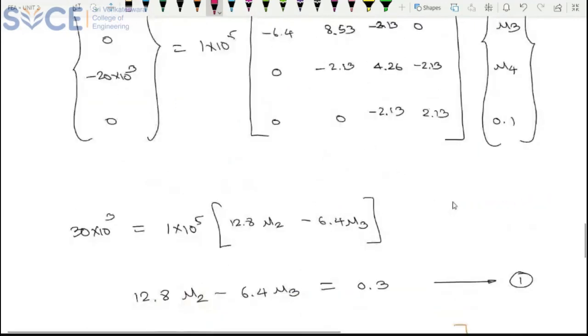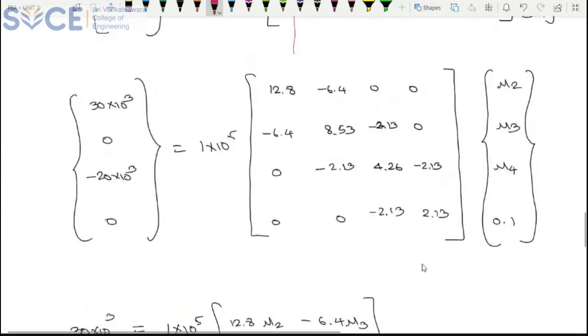Okay, don't use the last equation, even though you can get it as an equation. If you apply it, you have only one term, which is u4, so you will say that u4 is equal to 0. That is not possible. This equation I have to cancel. So first column: whenever you have the value of displacement, it has to be cancelled. But since I am using this value, I am not cancelling. That's it. So don't use the last column.